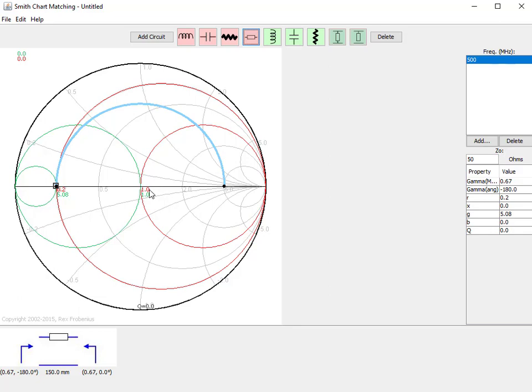But if we adjust the impedance of that line according to the formula for the input impedance of a transmission line, we saw that the input impedance is affected by the characteristic impedance of the line that we insert. So if we make that characteristic impedance the same as the square root of the product of these two terminations, we'll get an impedance match going on.